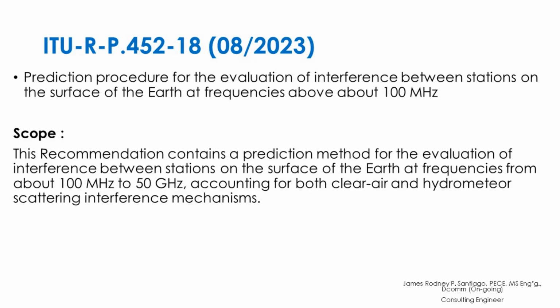The ITU-R P.1411, the latest version being September 2021, is a propagation model for short distance outdoor communication from 300 megahertz up to 100 gigahertz, meant for local radio networks, for line of sight and non-line of sight. Which means you have the direct line signal and then the Fresnel zones up to the radio horizon.